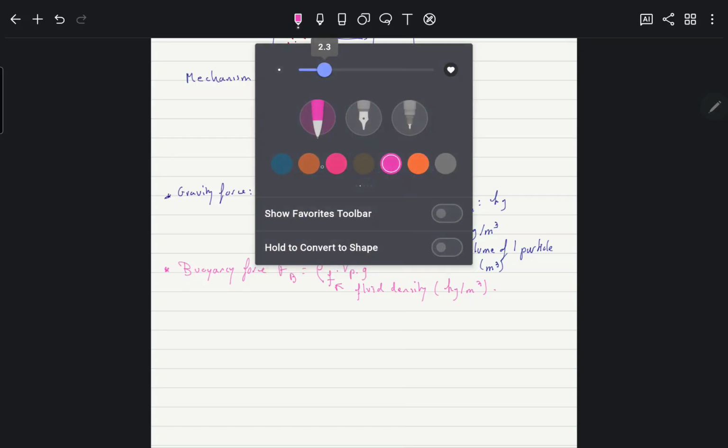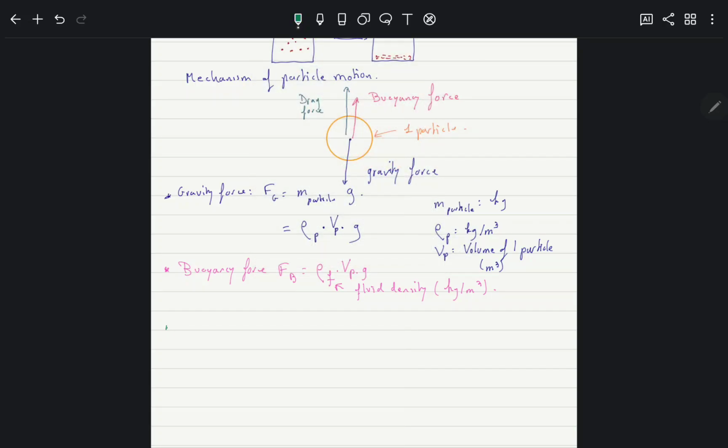And finally our drag force. The drag force, as we saw before, is expressed as Fd equals the drag coefficient, Cd, times Ap, where Ap is our projected surface. We'll come back to this a little bit later. Times 1/2 of the fluid density, times the squared velocity, so that's kind of a kinetic energy term here.